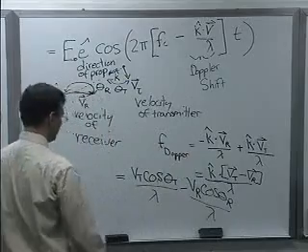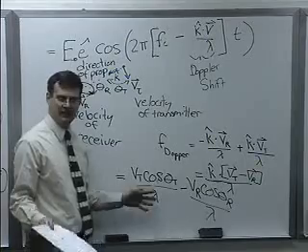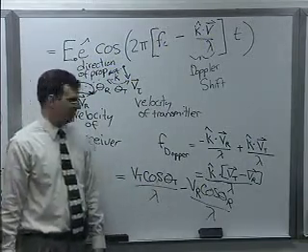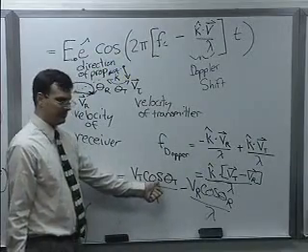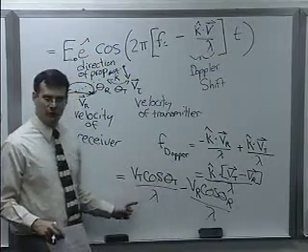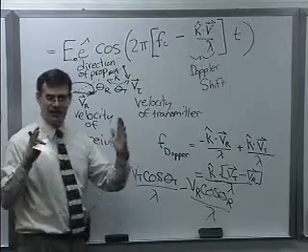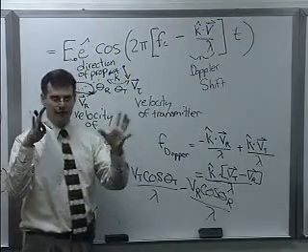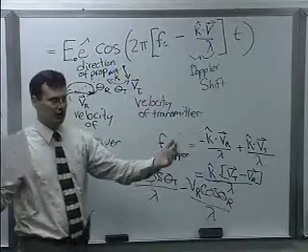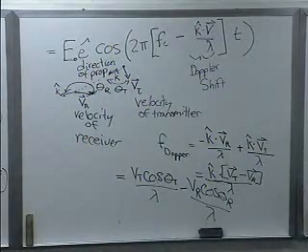And so if you ever want a rough back of the envelope calculation of what you'd expect the Doppler shift to be, you just assume that the cosine is 1, because it's never going to get larger than 1 and never going to get less than -1. So your velocity over the wavelength is a nice rule of thumb for predicting how bad your Doppler is going to be. If you can satisfy your comm link within that range, so that all the filters are set up so the signals can slide around that much, then you're in good shape. And so let's do a quick calculation just to get some numbers around this concept.